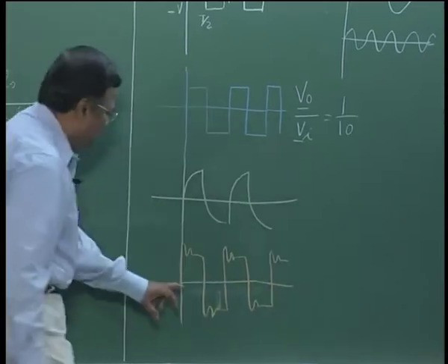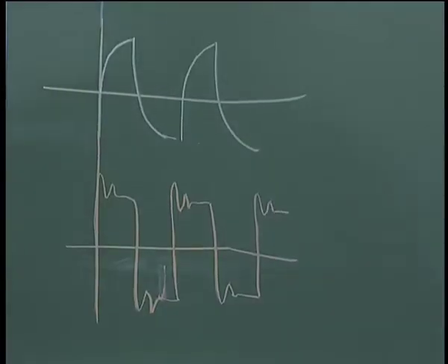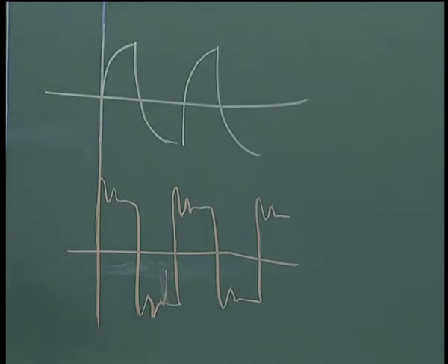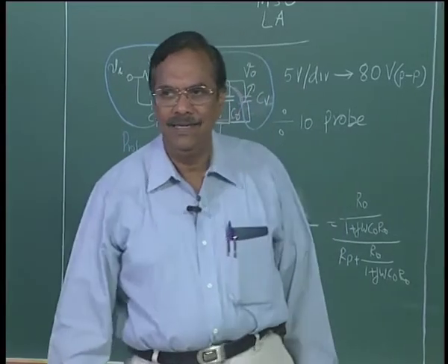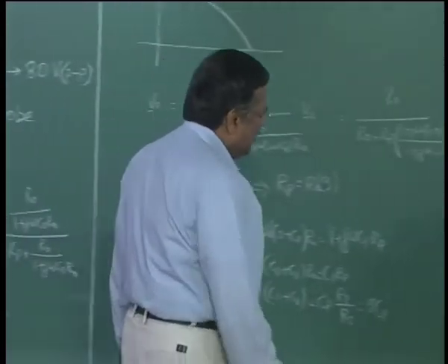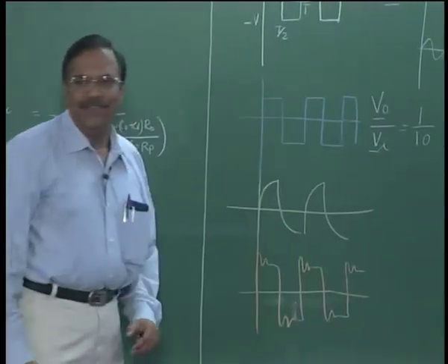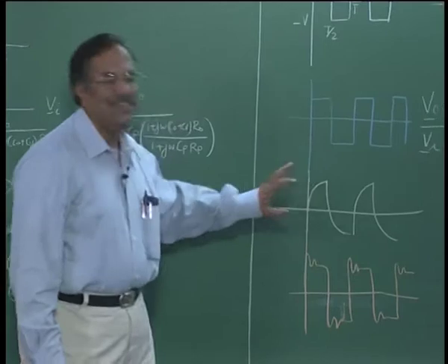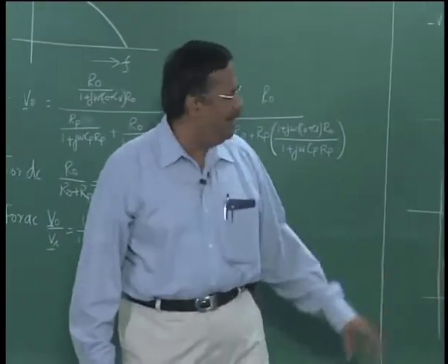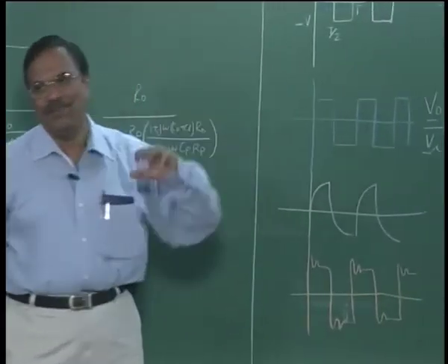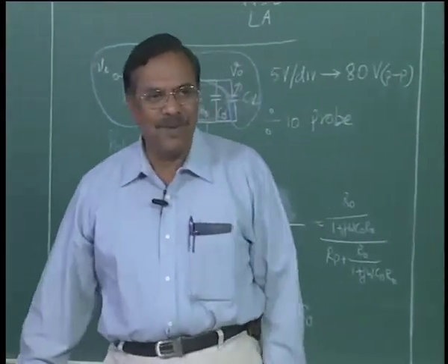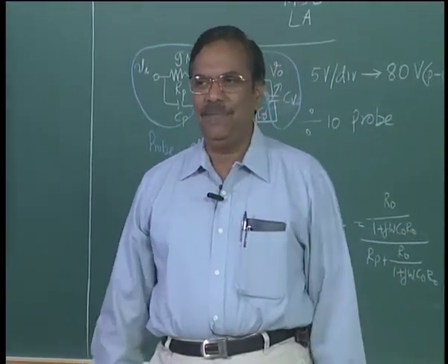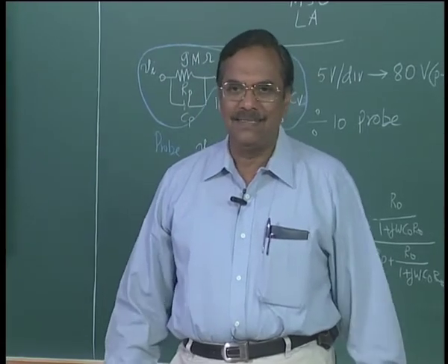Every time there is a plus V to minus V transition, there would be a small ringing, right. So in this case I know I have to increase CV, in this case I know I have to decrease CV, and if I get a perfect square wave on the oscilloscope, I know that the condition C naught plus CV is equal to 9 times Cp has been met, right.